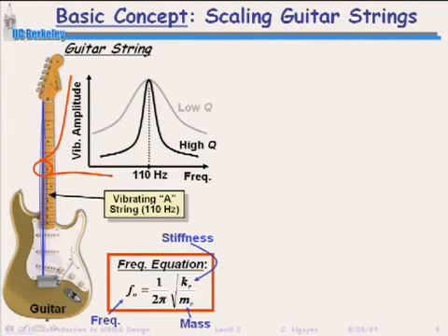It's only going to take on that frequency. That frequency is determined by the stiffness of the mechanical system divided by its mass. Okay, so if you think of this equation, very quickly you could see that if you could take that mass and lower it to very small values, you can drive this frequency up to very large values, and perhaps up to the gigahertz range if you make it small enough.